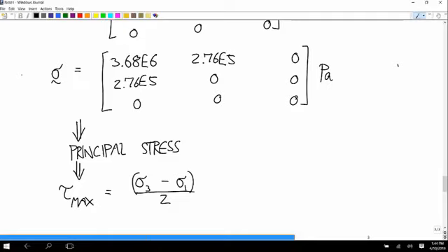And by the way, when I say a brittle material, you would never really make a beam out of a brittle material, I'm guessing, but maybe you would for some reason. What brittle means is that you can't deform it permanently very much before it breaks. Once it leaves that linear elastic range, you're basically done being able to deform it before it snaps in two.